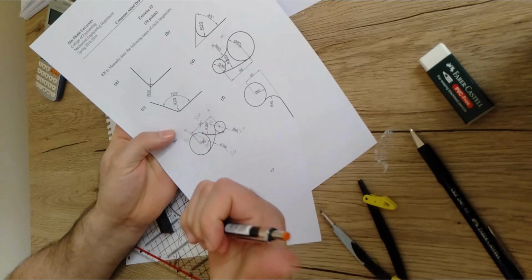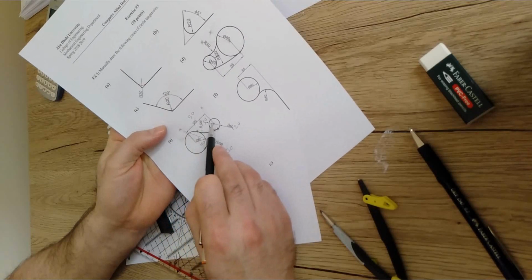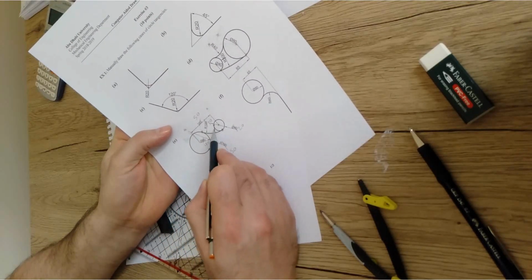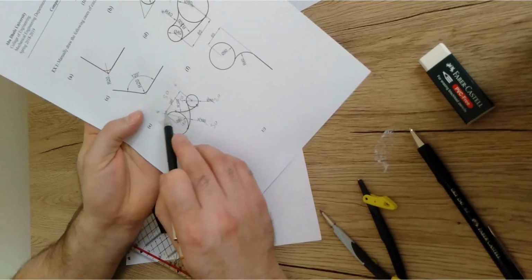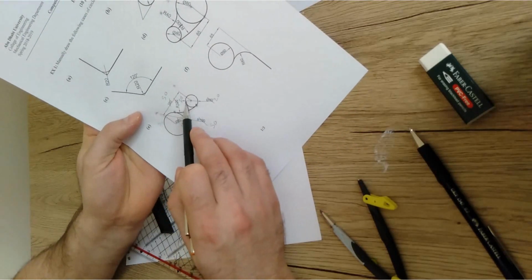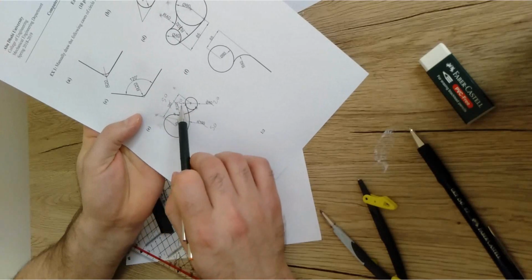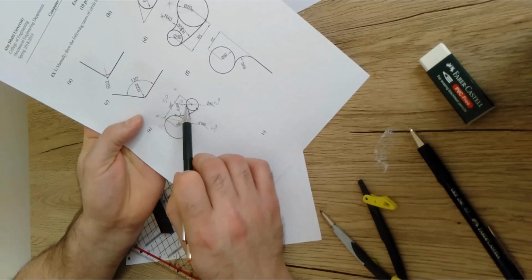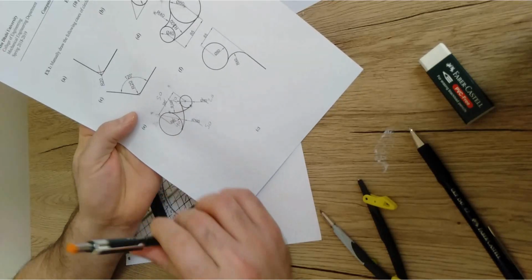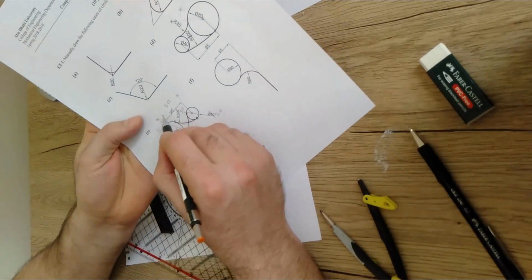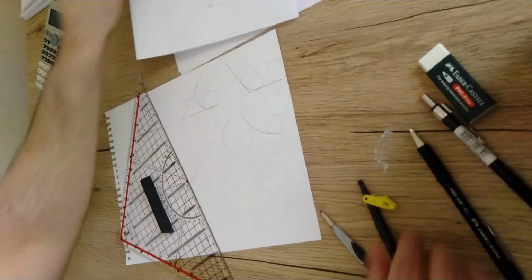So if I ask you to move from this point to the center point of the other small circle, we're going to go over the tangent point, because we are working over this curve. Since we're going to go over the tangent point here, we have to sum the radii. This radius will be summed to this one. So the sum of the two radii gives us 50 plus 10, because the radius of the small circle is already 10. This gives us in total 60 millimeters. So we're going to open 60 from the small circle, but 30 from the big circle. And this is what we're going to do.